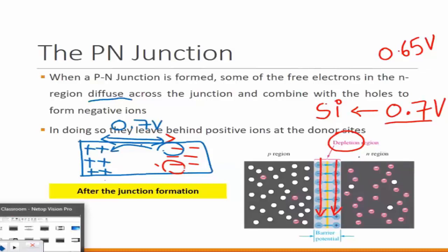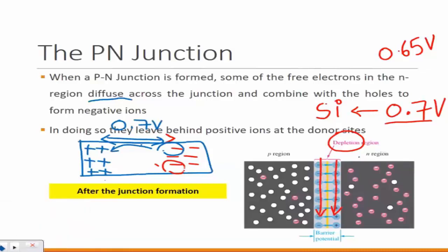Doesn't it add to the length of the barrier? This is only by default. Again, as I said, that value may change. For example, if you touch the PN junction with your fingers, that means you're raising the temperature. Correct? If you're raising it, then this voltage will go down. That means you need less voltage to overcome the barrier. We haven't talked about heat and light changing things.